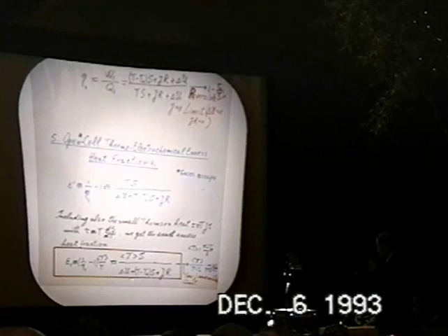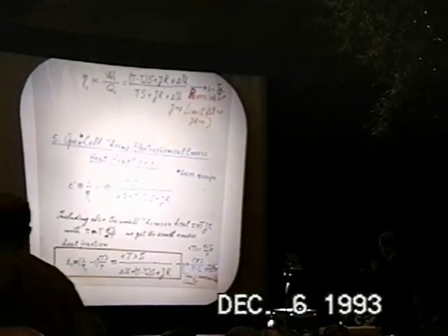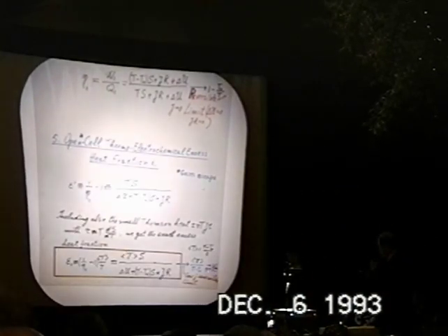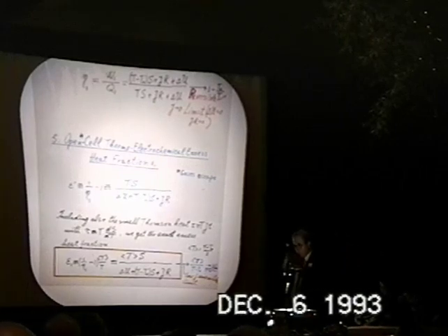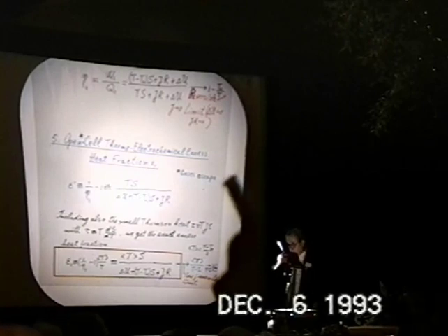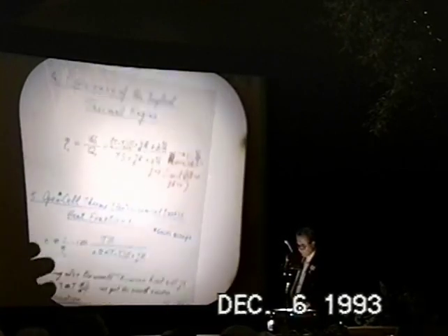And this is therefore the most important expression that I bring you to. When T minus T0 goes to 0, particularly in the mass flow regime, we can have very small temperature differences, which we measure very accurately, and we get enormous amounts of heat. It can go to infinity, and due to this situation, we can get it arbitrarily large.